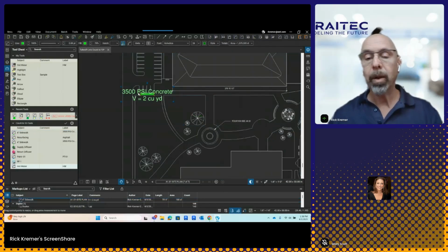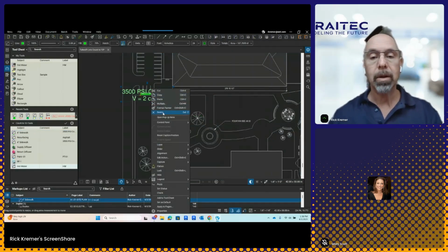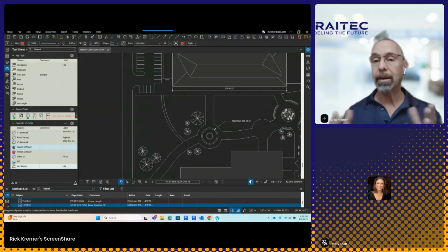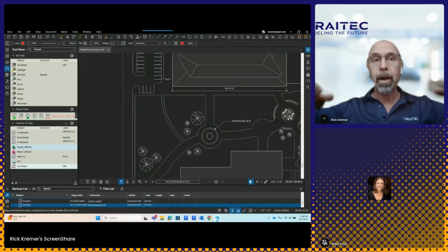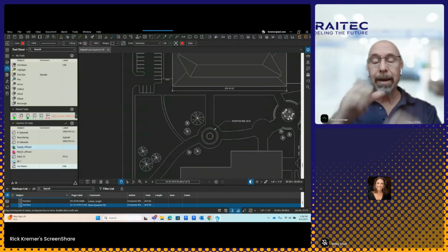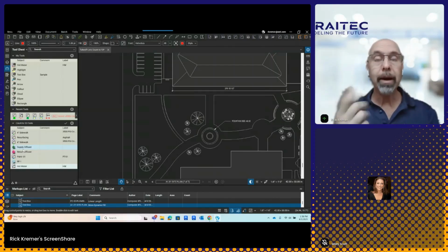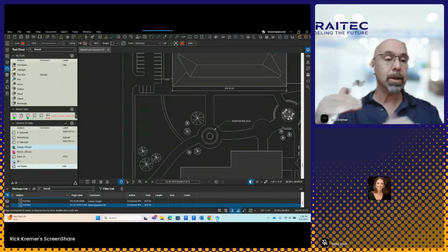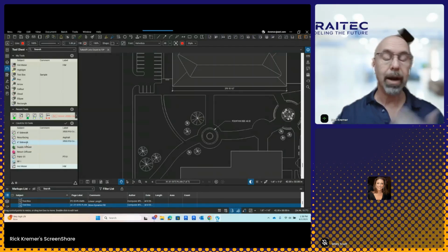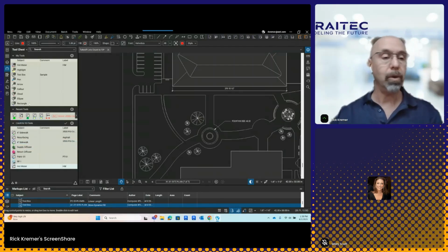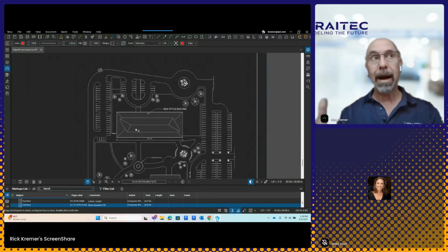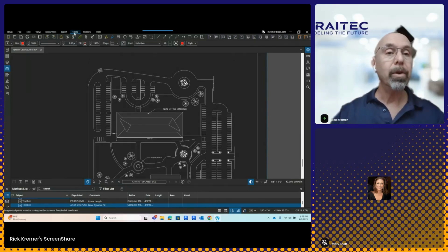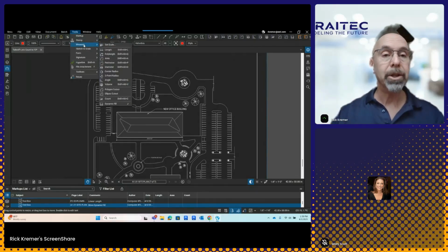Now, one of the things that I can do is, sidewalk is not paint, right? It has a volume. So we've done paint, which is a flat surface. We've done counts, but now let's do volume. Concrete is going to be in cubic yards. In this case, a 4-inch concrete. How much concrete do we need? Here's where I'm going to use the power of dynamic fill. To do that, I'm going to go over here to measure and enable dynamic fill.